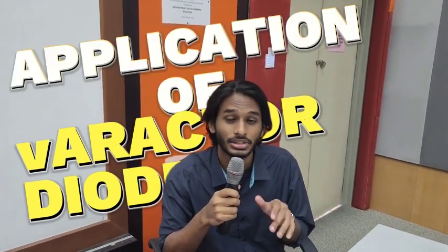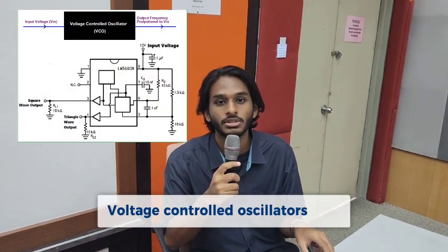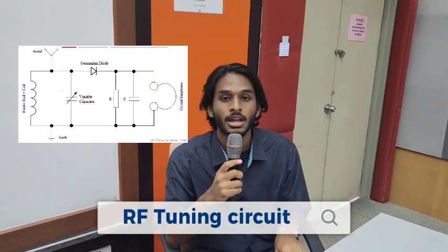So for the last part of the video, I am going to talk about the application of the varactor diode in electrical circuits. You already know the speciality of the varactor diode, it can vary the capacitance inside the diode. So this component is used in certain circuits such as RF design. I am going to talk about three applications, which are VCOs, the voltage-controlled oscillators, the second one is the RF tuning circuit, and the third one is frequency and phase modulators.